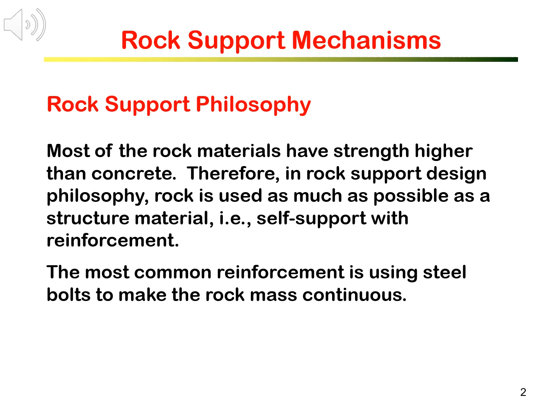However, because rock mass around tunnels and mines are fractured and jointed, rock blocks will fall down. We need to make sure the rock mass stays as one big piece and does not collapse and cave. That can be achieved by rock reinforcement. The most common reinforcement is using steel bolts to tie the jointed rock mass together to become one big continuous rock.